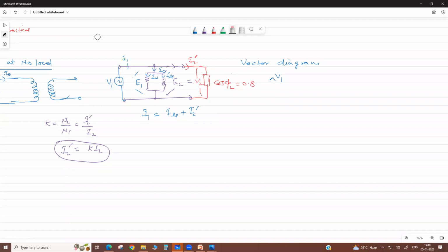Now the electrical load may be inductive, capacitive or resistive. It means there is a load power factor. When we connect a load of some power factor, the overall power factor of the alternator or transformer changes. That's why their ratings are in kVA, not in kilowatts.